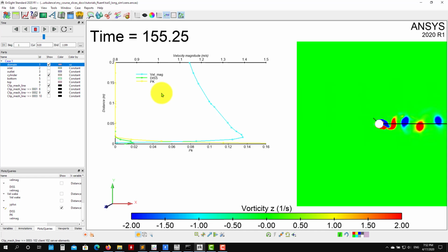budget, the turbulence budget. So you have production and dissipation, or destruction. Some books and references call it destruction, dissipation, and then production. Remember that we're in equilibrium, so they are kind of similar. As you take the integral of everything, you will see that they are very similar. But remember that the maximum production is in the buffer layer, and then dissipation goes to